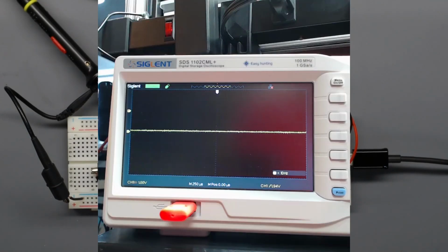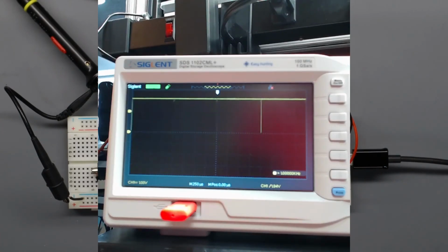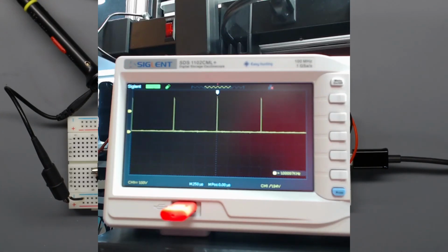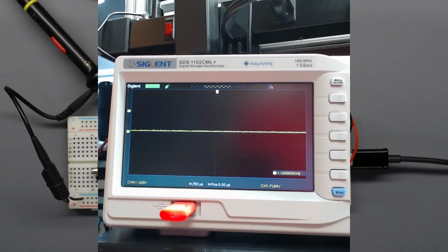Now let's look at it on the oscilloscope. Here you'll see it going full on, and then now full down. Again, full up, 100%, back down, 0%. So that is how you would do fading and variable speed control with an electric motor. Of course, some motors you don't need to accelerate up and decelerate down, but bigger motors, certainly that's a good thing to do. Otherwise, you can cause a number of problems with your drive circuitry.